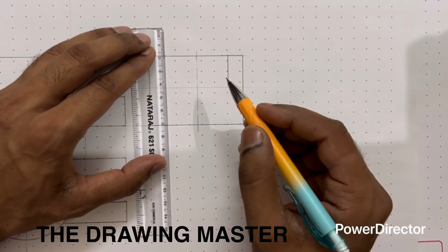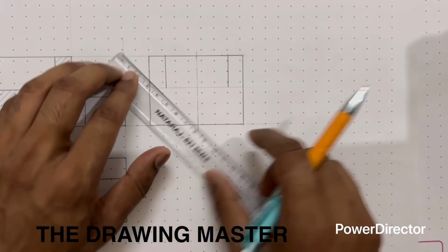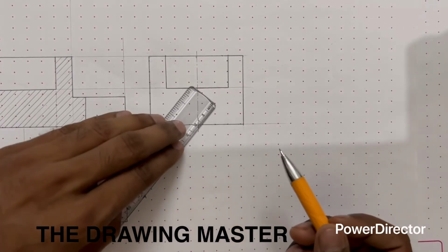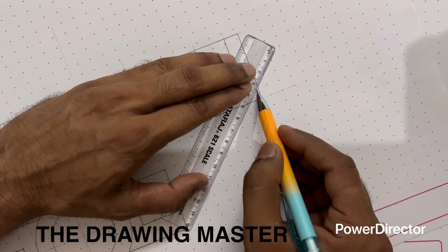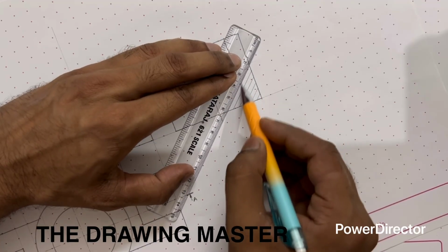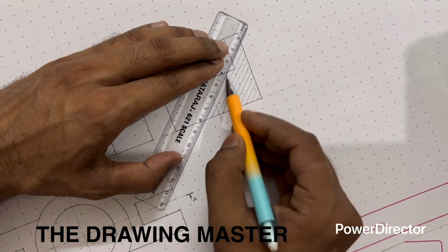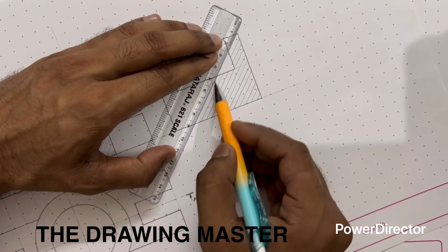After doing the cutting, after adding the cutting plane, this part will no more be hidden. So now this is the sectional side view of the object. Sectional side view of the object, and in the rest of the part you can do the hatching here. This is the third step. This is the full sectional side view of the object.